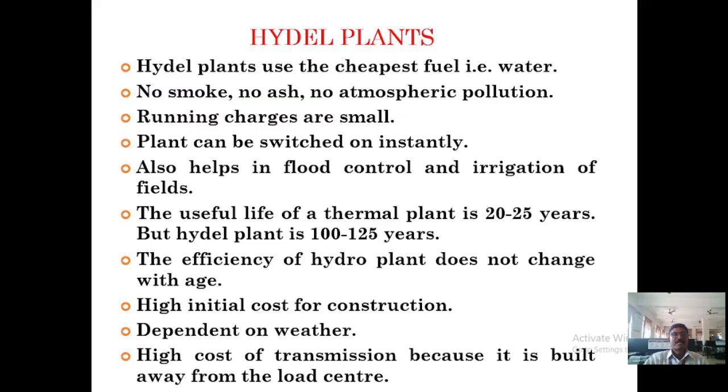The next source is hydel plants. Hydel plants use the cheapest fuel, water. About pollution, it is pollution free: no smoke, no ash, no atmospheric pollution. The running charges are very small compared to other conventional plants. The plant can be switched on instantly. A thermal power plant takes time to shut down, but a hydroelectric power plant may be started instantly. It also helps in flood control and irrigation of fields.